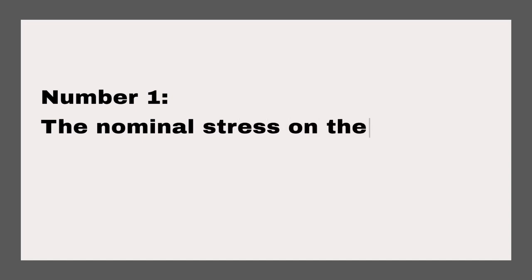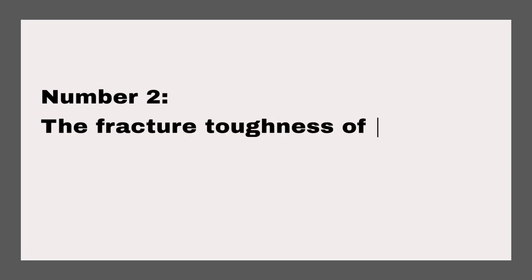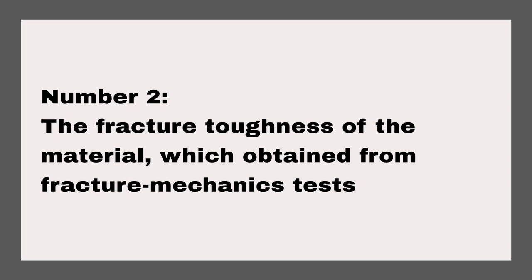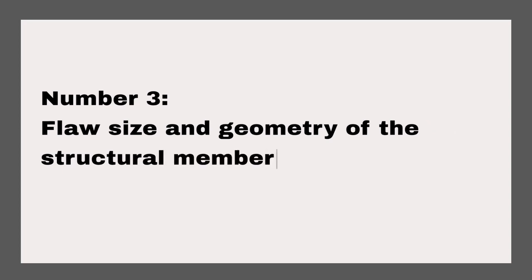There are 3 pieces of information required. Number 1. The nominal stress on the member, which can be obtained from structural analysis. Number 2. The fracture toughness of the material as obtained from fracture mechanics tests. Number 3. Flaw size and geometry of the structural member being analyzed.